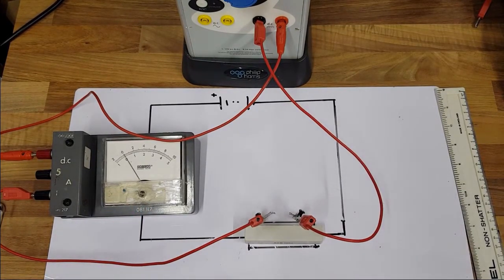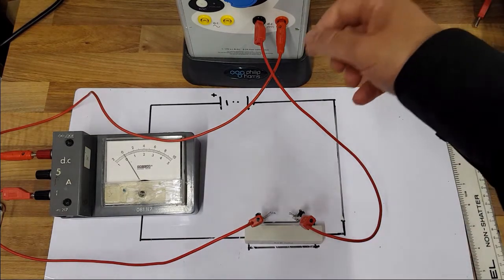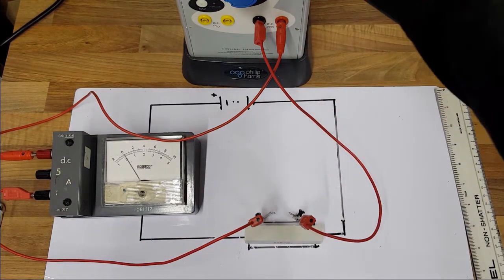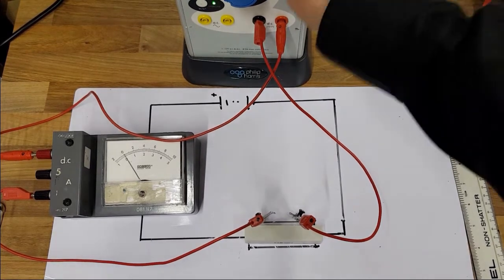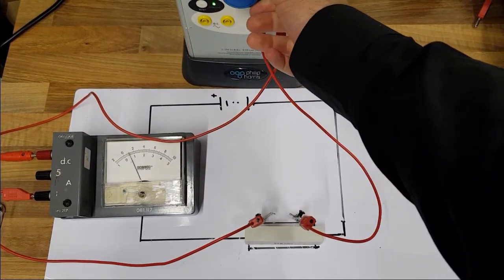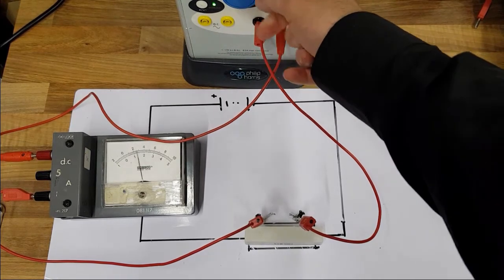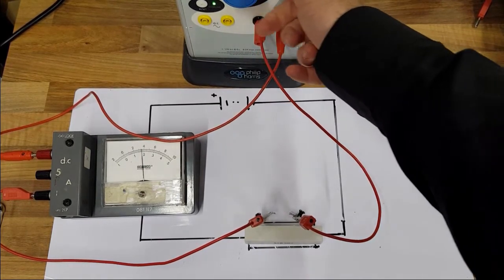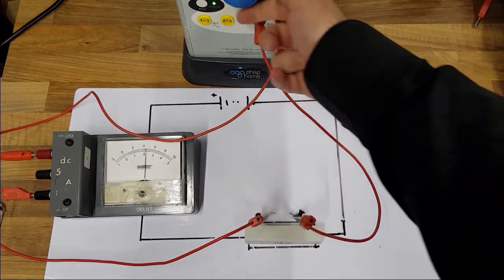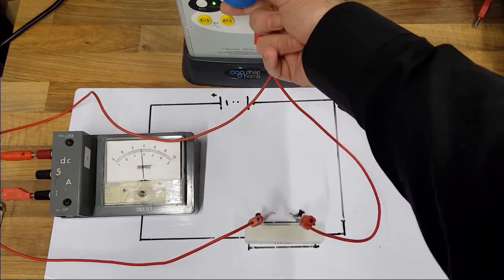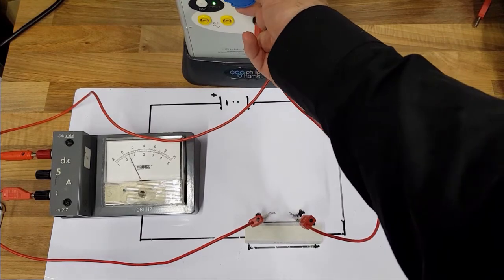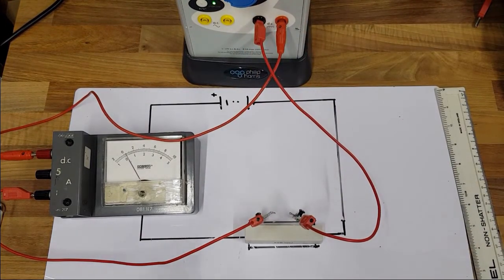So what I would do, notice we've not got a voltmeter in here yet, we're doing that on purpose. What I'm going to do is turn on the circuit and see if we actually have any current flowing through it. Turn up the power supply, you can clearly see that we have a current flowing through. So all the wires work, the resistor works, everything is fine. Now it's only at this point that we think about popping our voltmeter in.